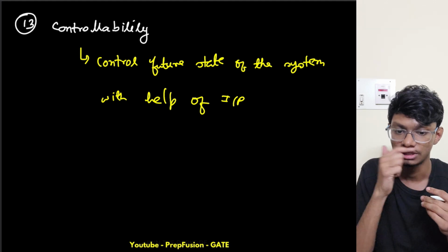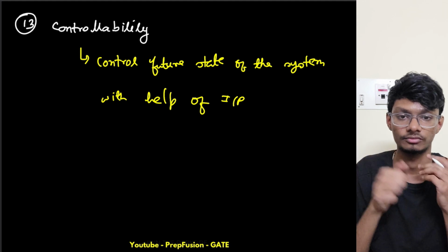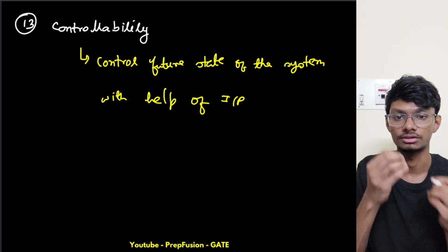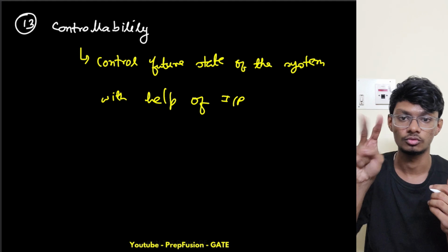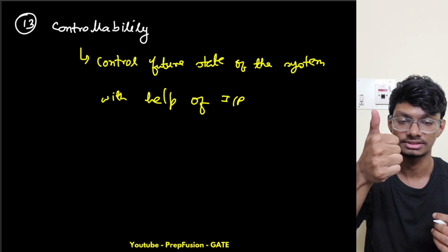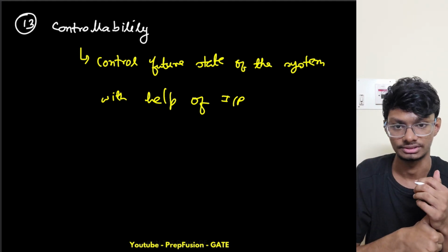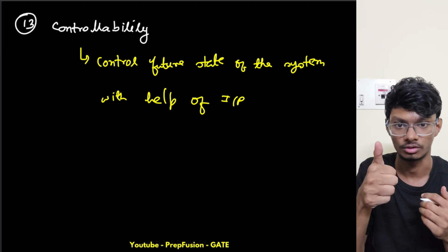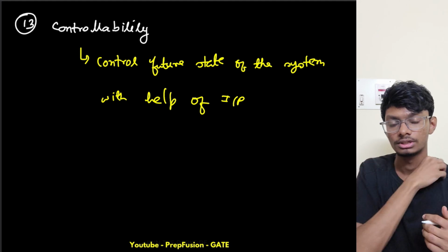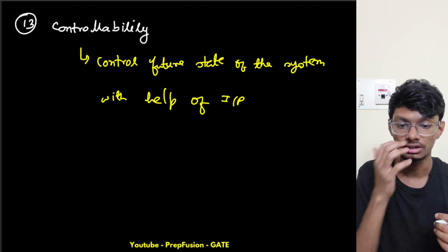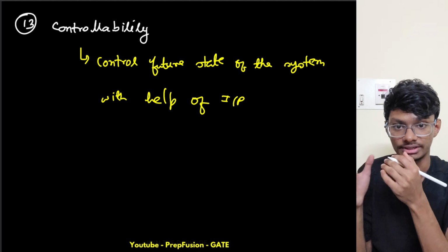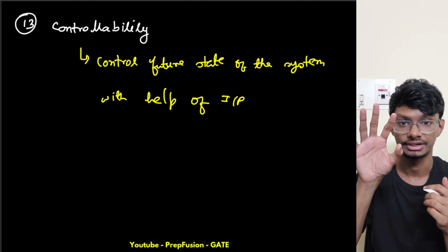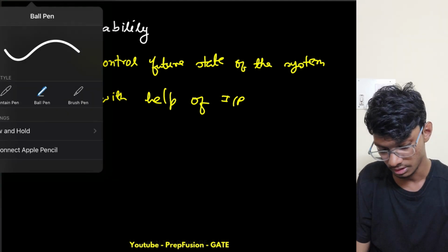Controllability Kalman's test. We can figure out whether the system is controllable or not with two methods, right? First one is Kalman's test, and second method is Gilbert's test. So what does Kalman say? Kalman gives us one matrix. The proof that I do is not important, the main outcome, the conclusion, is important. So with Kalman's test, what we did was this QC, the controllability matrix.